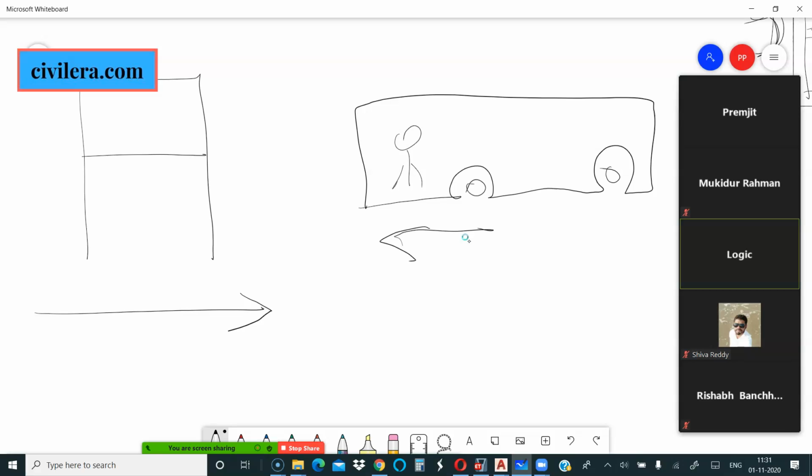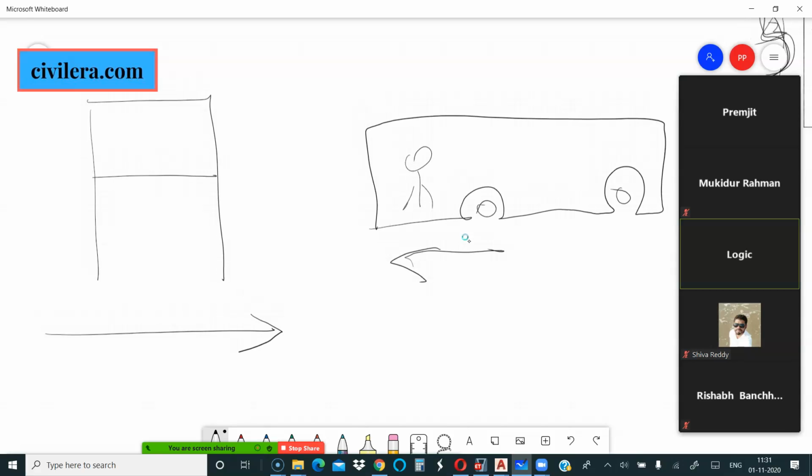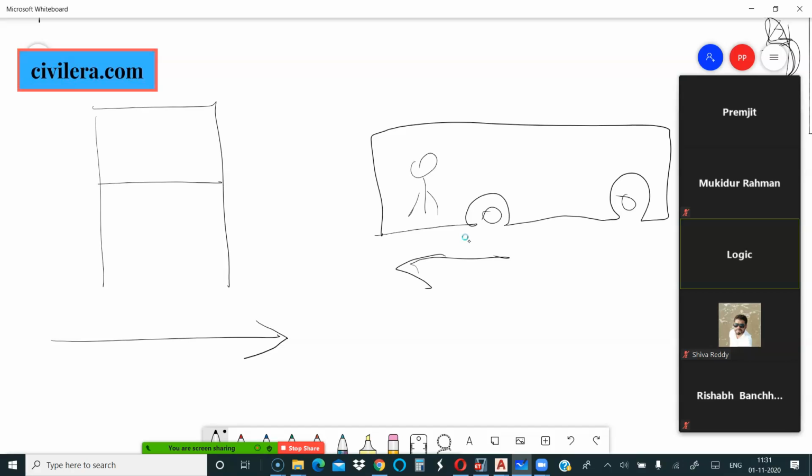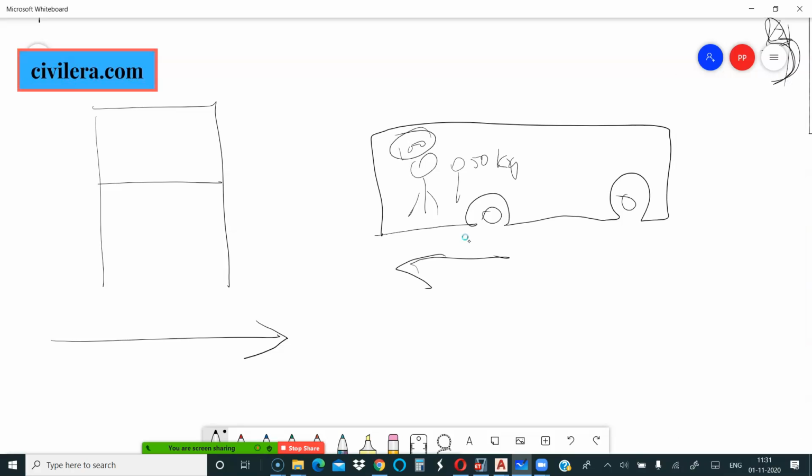So that exact inertia is what an earthquake is, nothing else. Based on your weight, if two people are traveling, one with a larger body mass and one with a lesser weight, the 100 kg fellow is going to have more problem because the mass is more and the lateral inertia created due to your own weight is going to trouble you more.